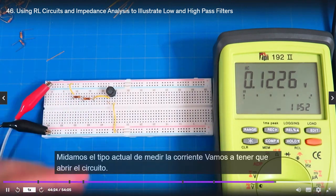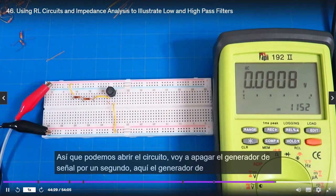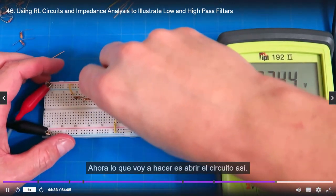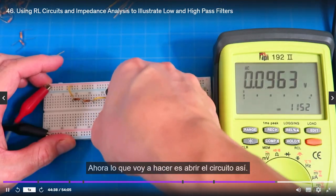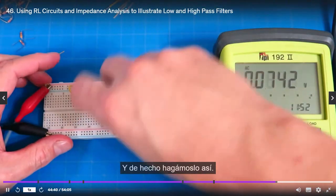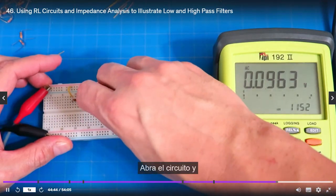Let's measure the current. To measure the current, we're going to have to open up the circuit. I'm going to turn off the signal generator for a second here. Signal generator is off. And now I'm just going to open up the circuit like so. And as a matter of fact, let's do it like this. We'll open the circuit up.